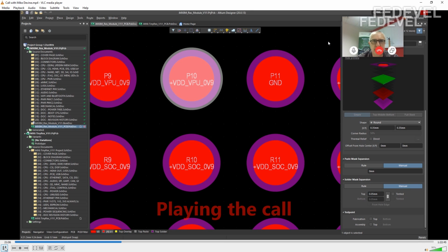So the microvia separates away from the buried via at high temperatures, so expansion, it goes open circuit. When the unit cools down, it goes closed circuit and then is functional again.